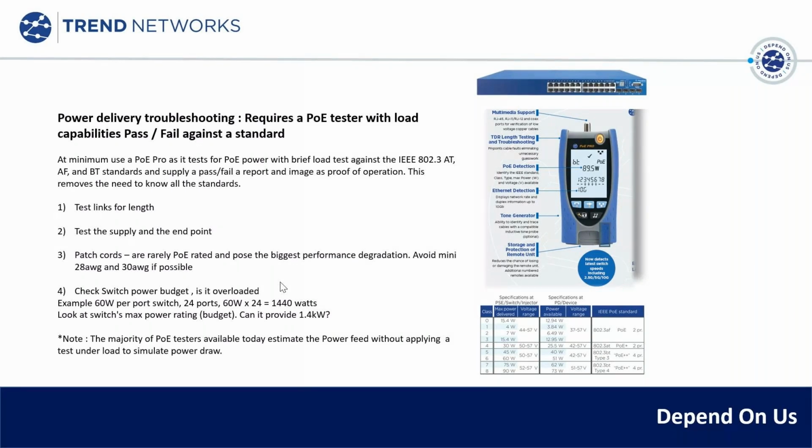And they can work on a short link. It's possible. We've seen the introduction of 28 AWG and 30 AWG is a big concern. However, they can work on short links. How to test? Well, at least you can apply a load tester.